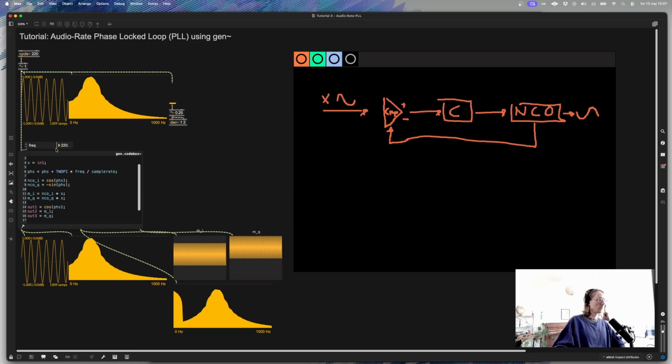And as soon as we have them in the same frequency, this low frequency component stops moving essentially. And this low frequency component is what we're interested in, and the high frequency we want to filter out.